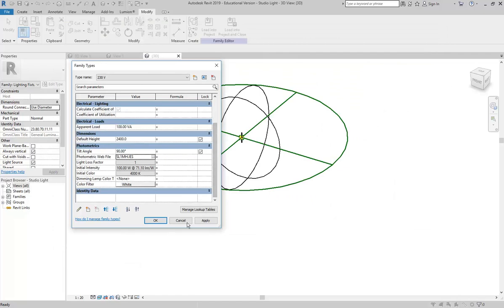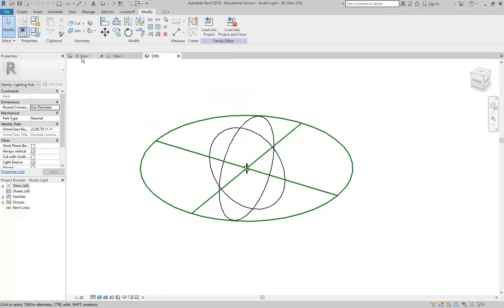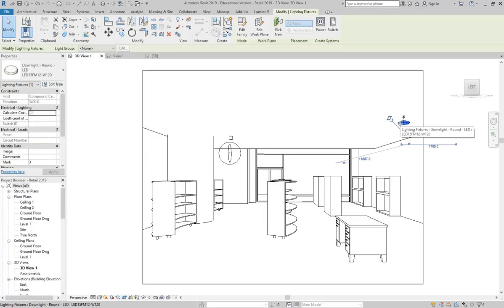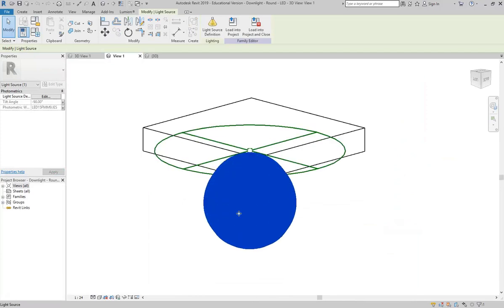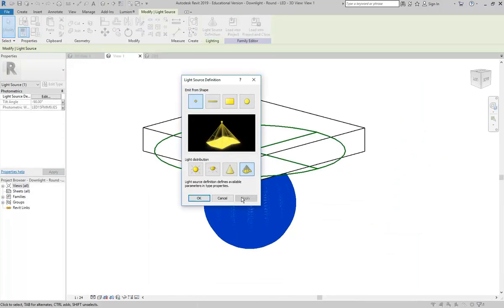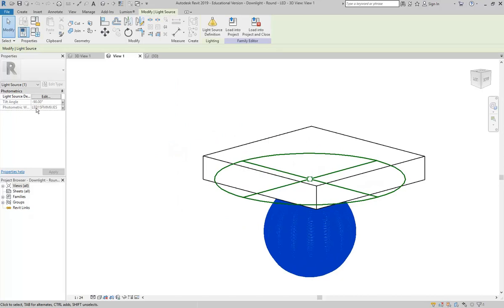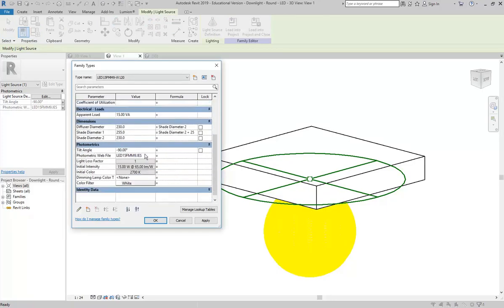And so more and more now with Revit, not even worrying about 3ds Max, even just in Revit, you'll see a lot of the newer lights. So this one here that I brought in from the new library, that LED light, I guarantee you it will be, yeah, there we are, another photometric one. In other words, another web distribution. So again here, when you select it and look here and you see that web one, it means it's using a file they've decided is good. And here's that file, or that's where you can see that it's set, and in family types you can see the name of the file really easily.